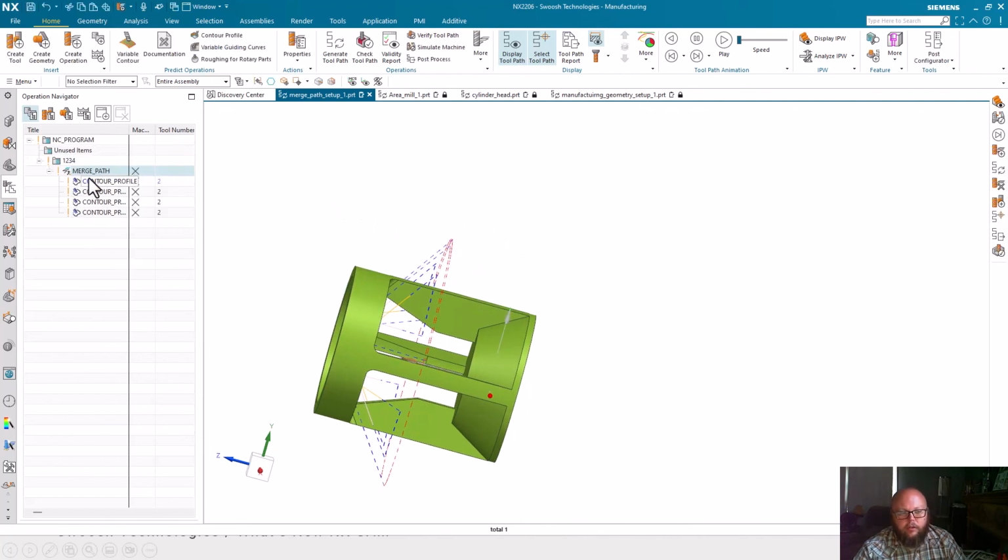Now this is kind of cool, especially if you build in logic into your post-processor in start of path, end of path events, to do things like send the machine tool home or clearance to Z, Z homing or things like that. A little bit more efficient toolpath. Kind of a cool thing that's been out just for the last couple of releases now. So something worthwhile looking into.